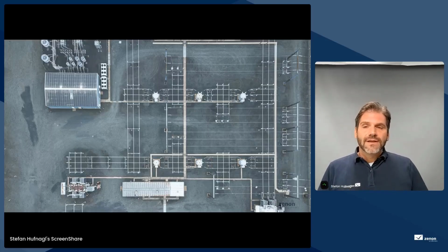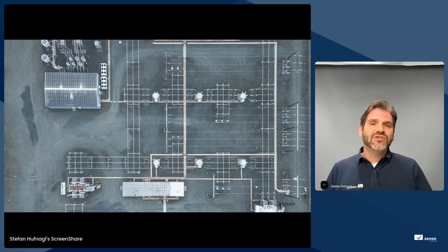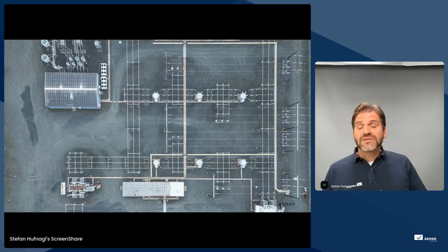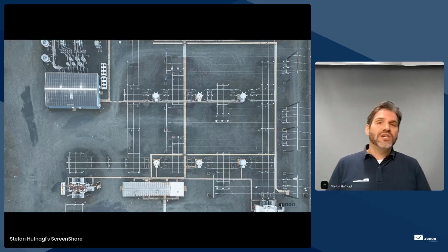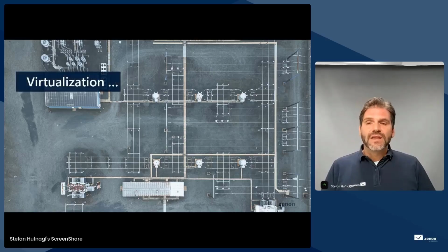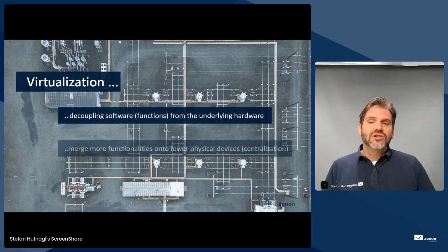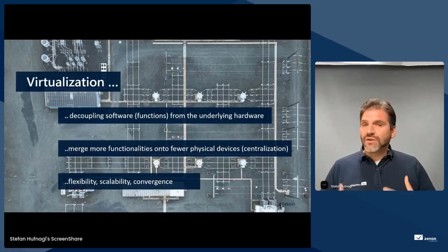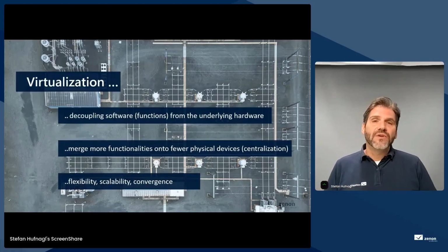functions. Now, substation automation solutions typically comprise a large variety of hardware and software components from different vendors, such as protection, automation and control equipment, HMIs, gateways or security systems, for instance. And here, virtualization tries to decouple software and software functions, especially from the underlying hardware, in order to aggregate and centralize functionalities on one single platform.